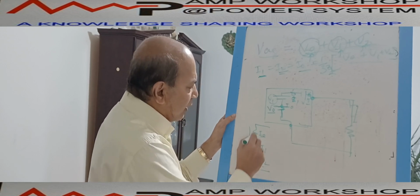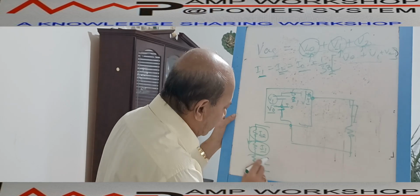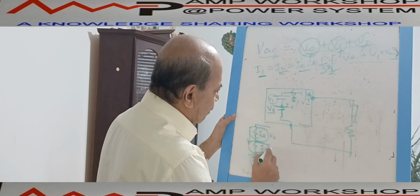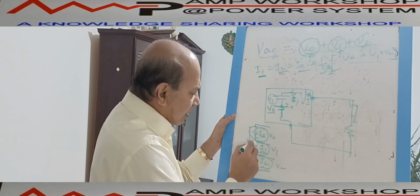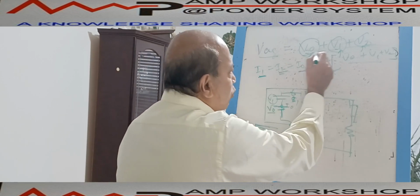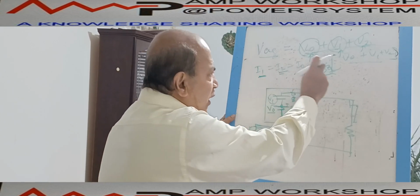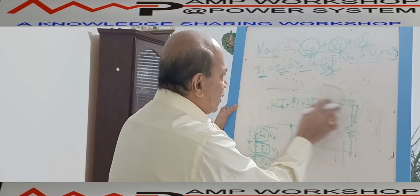If all these three currents are equal, that means it is flowing through a series connection. That means the zero sequence network, positive sequence network, and negative sequence network are all connected in series, because this sequence network has a voltage V0, this one has a voltage V1, and this one has a voltage V2. These three voltages are connected in series, and this impedance is also in series. Then only is it possible that all the currents are equal, and the voltage is the sum of these three. From these two relations we can conclude that for a single line to ground fault, the zero sequence, positive sequence, and negative sequence networks are connected in series.